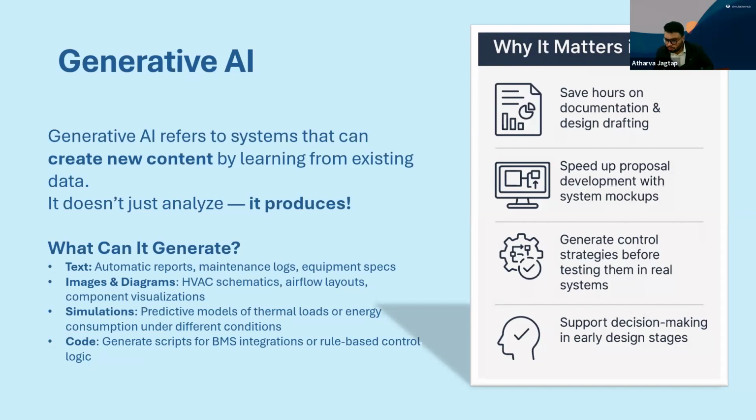Then talking about simulation. Yes, we are domain guys and we are more concerned about simulations. So it can also generate simulation inputs for us. It needs some prompt-based inputs: what type of simulation you want, what type of inputs you want, what type of schedules you want, and based on those conditions, it can actually generate inputs for you. If we take the example of EnergyPlus, it can actually generate inputs for IDF files.